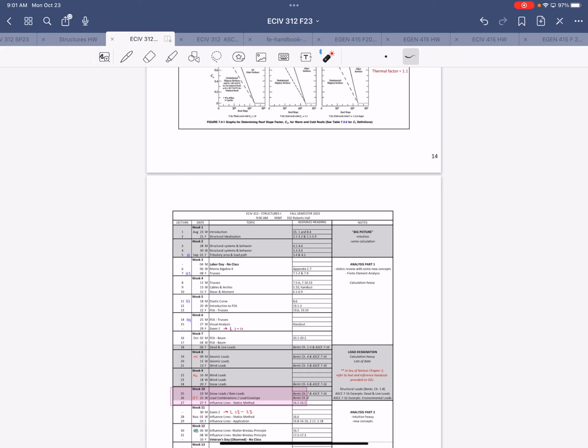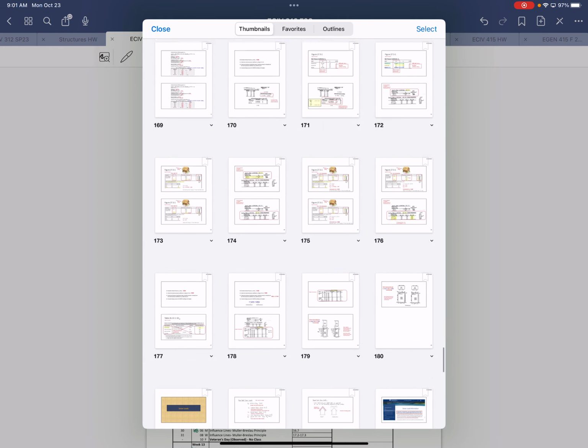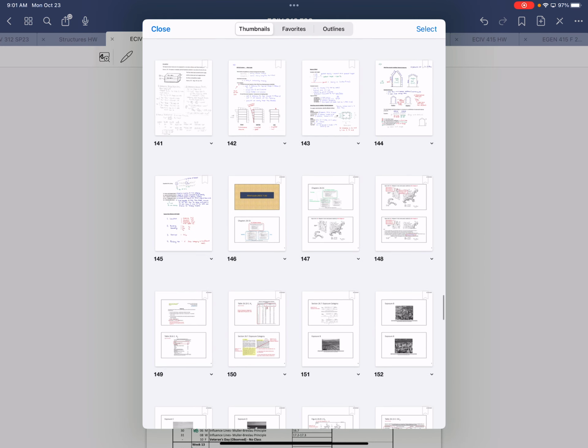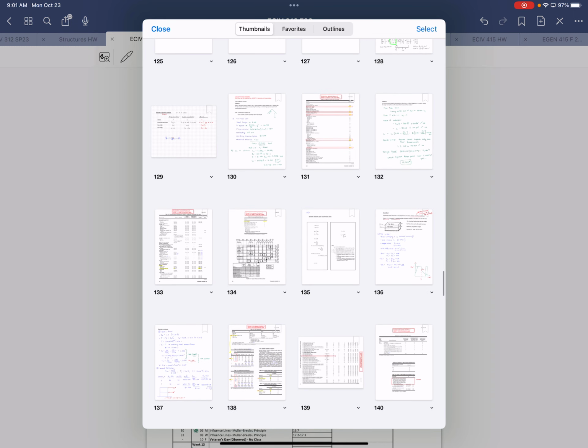Yeah. For the homework, I think it's question 1 or 2. There's two systems in both directions. For the seismic loads, once we go through, do we just add those together to get the total shear force? Because you're talking about the R factor, the seismic shear, the base shear. I think you get the total shear before going to the individual floor. Do you just add that together to get the total, and then do the vertical distribution?